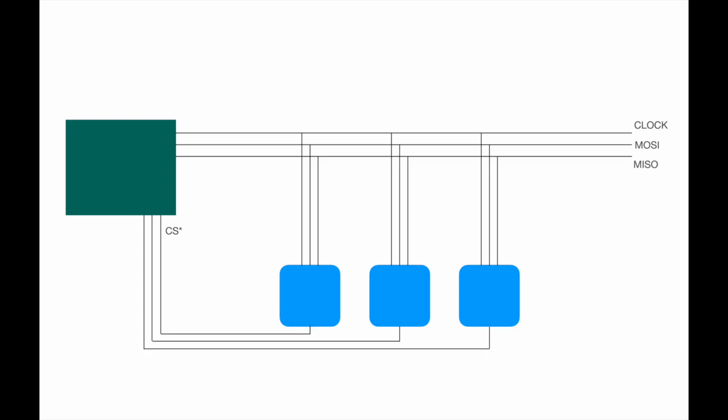In its most common configuration, there are 4 signals for an SPI device: 3 shared lines called clock, MOSI, and MISO, and 1 individual line for each device, the chip select. MOSI and MISO are the data transfer lines. Let's pretend that MOSI stands for microcomputer out serial in, and MISO for microprocessor in serial out. Those aren't the real names, but that's what I'll use here. So those are the data transmission lines in each direction to and from the computer.